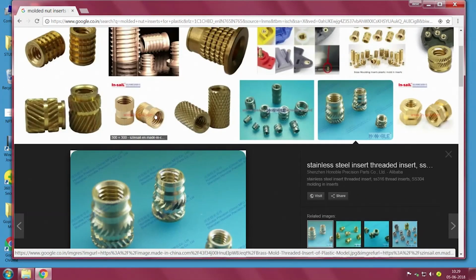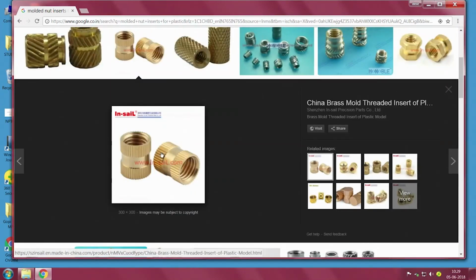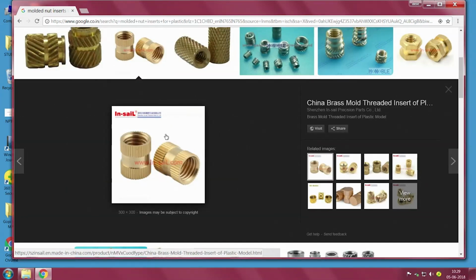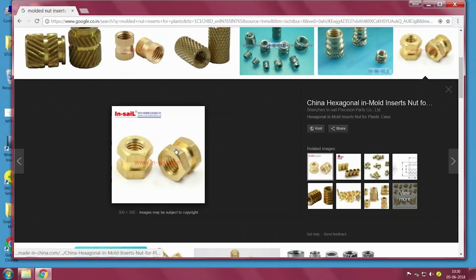These are the most common thing which are used in normal injection molded plastic. You see that one had that knurling, but it looks like a herringbone gear. This one has straight knurling and it has a small step inside. So, maybe it is patent, maybe it is there, and then you see here this could be a very common thing which even you can make, that is take any long hexagonal tube, they are all usually available up to 50 to 60 mm long, and then part it and then afterward cut a groove, you have an object that can be easily used in injection molding.